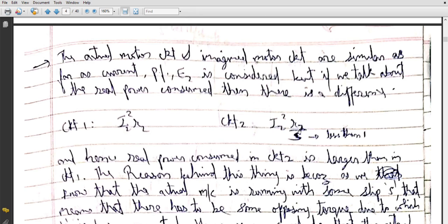If the motor is rotating only the shaft, then some mechanical power is extracted for rotating that shaft, and hence slip is generated. If the motor is rotating the shaft plus some external load, then the machine provides mechanical power equal to that consumed by the shaft plus that consumed by the load. So this is the significance of the slip.